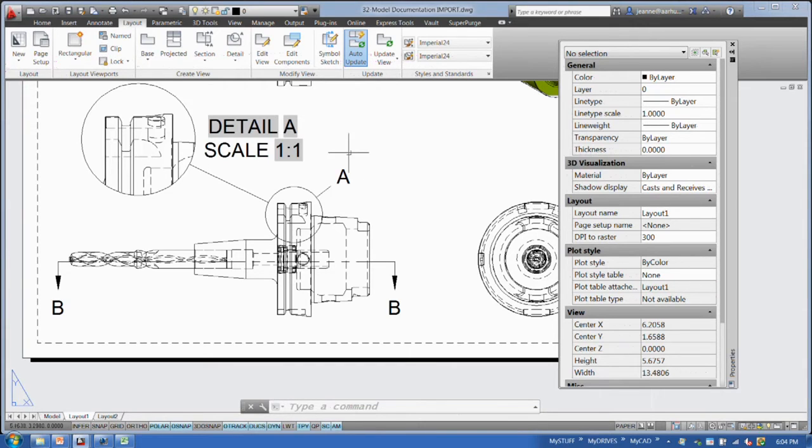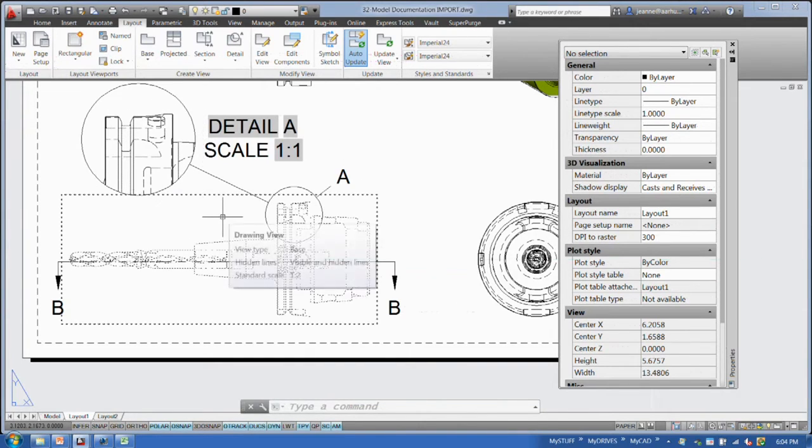Yes, all the views update. So it's an Inventor model, so I didn't link it in, but if you came in and you modify the 3D model, all the views update. Now, if you turn off the automatic update, they all get a red square around them telling you that the model documentation views need to be updated, and you just update them. There's an update view on them.